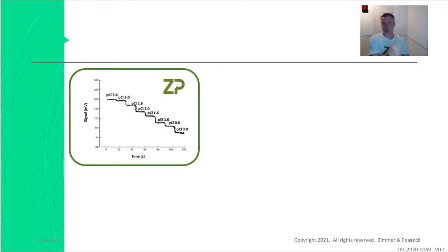and Ahmet has asked a question online as well. Ahmet, specifically to your question, we're measuring open circuit potential. We're specifically just measuring the voltage between the two electrodes using essentially a very high impedance so that we don't get any flow of current. So the technique, we would call it open circuit potential. You might just call it voltage reading or a potentiometer. It's really important not to allow current to flow.